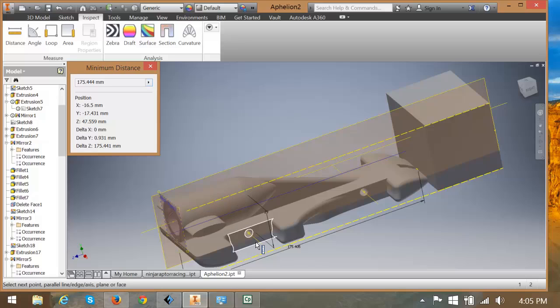Now the milling machine will not produce the axle hole locations for you to drill. You need to set them up with a bit of code yourself when we come to that part of the program, and I'll show you how to do that. But we need some references, some dimensions that relate to the axle holes, which are 6mm diameters. They have to be because the milling tool is a 6mm bull-nosed cutter, which means it has a radius of 3mm and a diameter at the tip, and on the shaft of the drill, of 6mm. So these axle holes have to be 6mm, so make sure that they are.